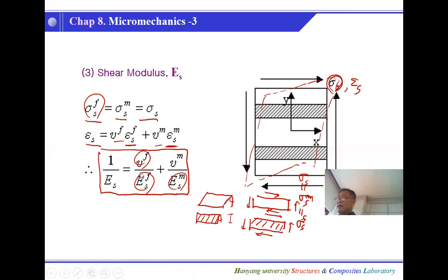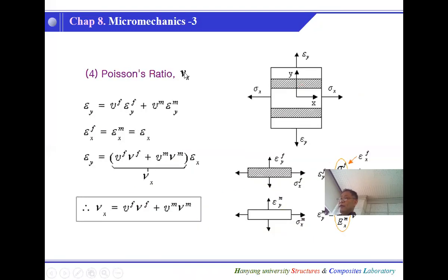Okay, so this is the shear modulus, and there is another step to calculate the Poisson's effect. We follow a very similar step as before, and there could be other terms, but we drop them, and this ply Poisson's ratio will follow the rule of mixtures. And this is the fiber and resin Poisson's ratio.